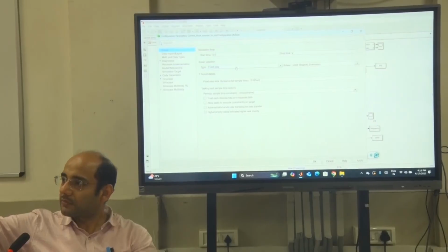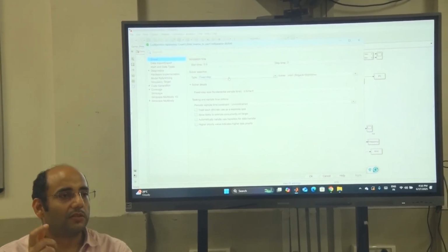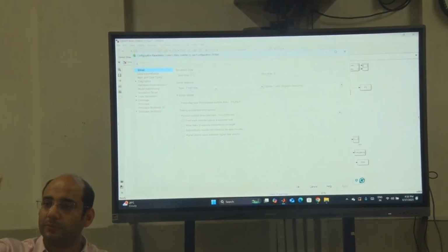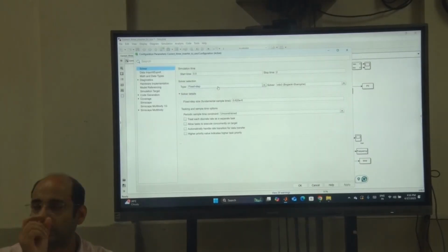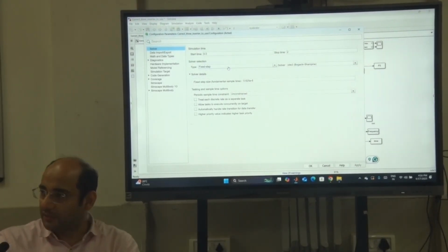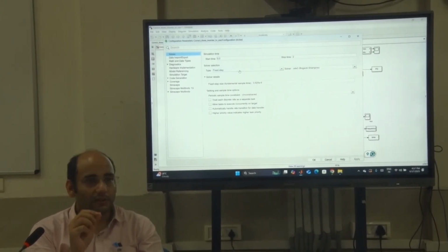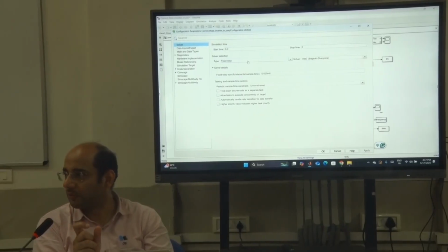What will you get? A triangle. Okay. So that is how important your sampling is. To have a proper smooth sinusoidal waveform, you need sufficient sampling so that you can recreate the sinusoidal signal. So it is always advisable to put in a correct sampling number.